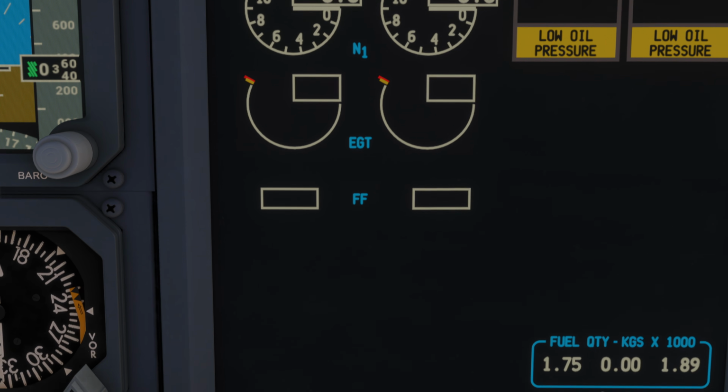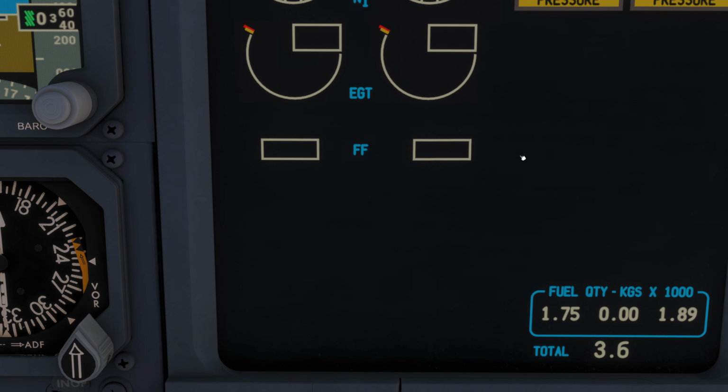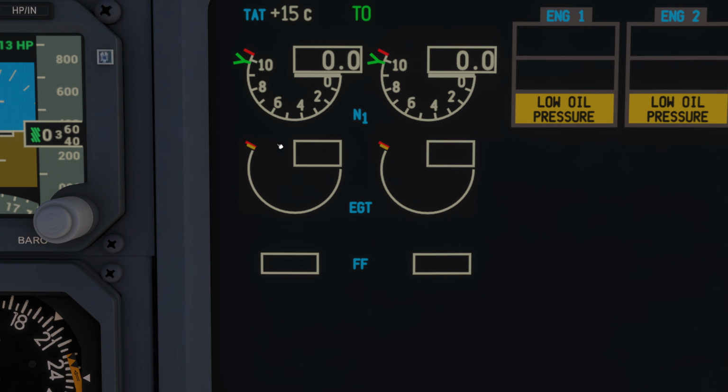Now from there we're moving a little bit further down and we got the fuel flow. Now fuel flow, you never really know how important that really is, because, well, in some cases airplane manufacturers are not even showing it over here. So for example in the 737 it's optional, the 777 doesn't have it up here at all. But what is fuel flow good for? It generally tells us how much the output of the engine is supposed to be.